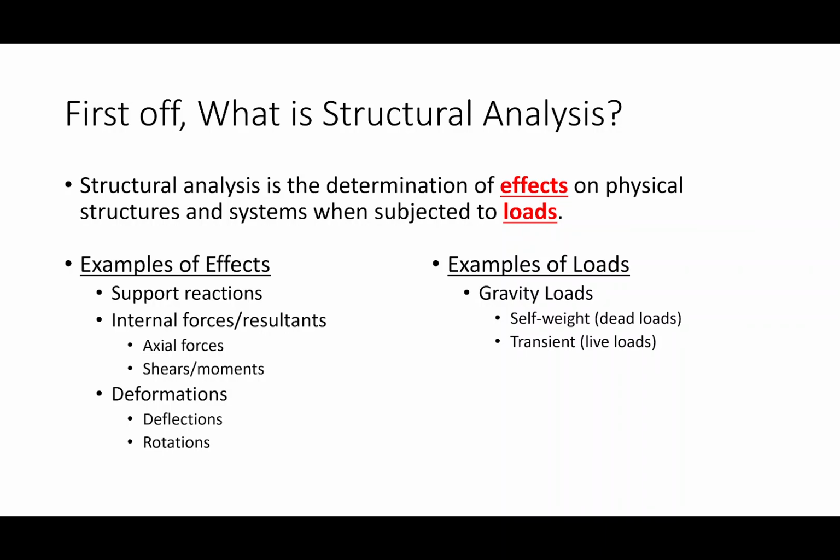Gravity loads are those that act in the direction of gravity. Self-weight, or the weight of the structure itself, we tend to call dead loads. Occupancy loads or transient loads, we call live loads. We'll get into more specific definitions later, but I tend to use the term occupancy load quite a bit